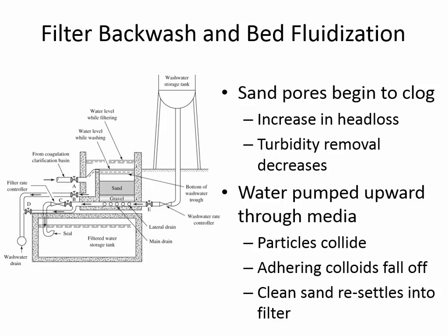So we pump the water up through the media. The particles collide, meaning the sand that's covered with a coating of colloid particles, it's kind of dirty sand, floats around during backwash and bangs into other sand particles. Then those particles that were stuck in the sand filter get wasted. You can send it to wastewater treatment, or you can put it into a river, because really all it is in many cases is clay particles.